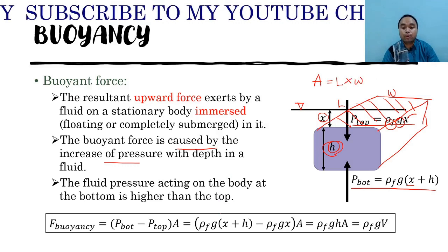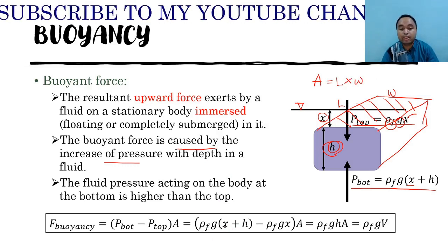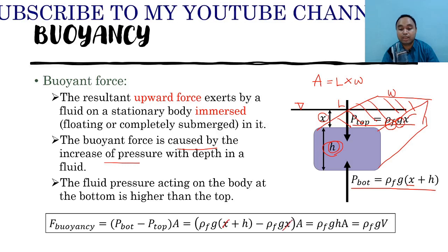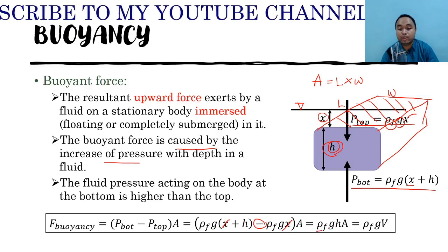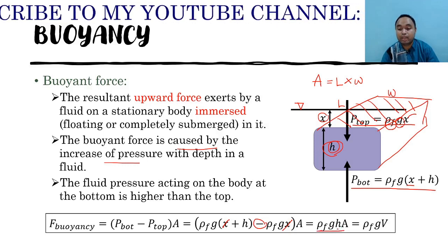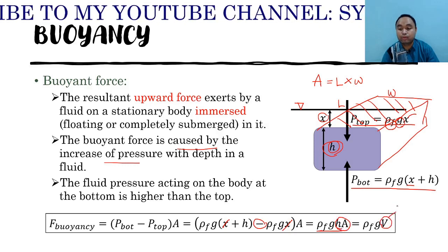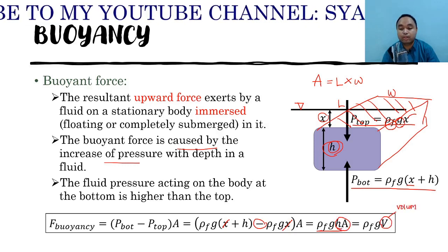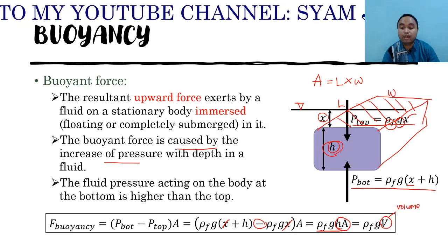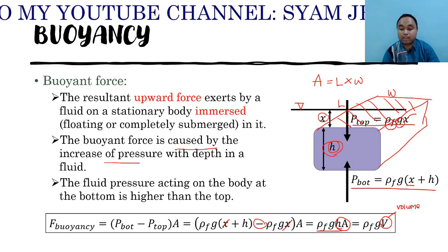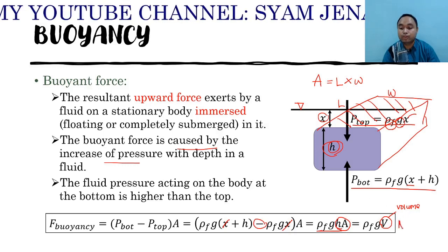Okay, if you put that in the equation, you can see that this x and this x cancel out due to the minus sign. So at the end, the equation becomes this way, and the h times A over here equals the volume. So the equation of force of buoyancy is equal to the density of the fluid multiplied by the gravitational acceleration multiplied by the volume, and the unit for this should be Newton.